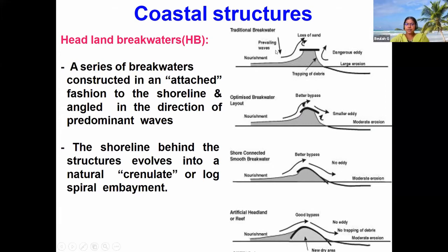Here you can see the prevailing tidal waves penetrate inside, and this causes very dangerous eddies. You can see a large portion of erosion happens over these regions. With optimized breakwaters, the eddy currents are comparatively lesser than in the previous one, and moderate erosion is caused.